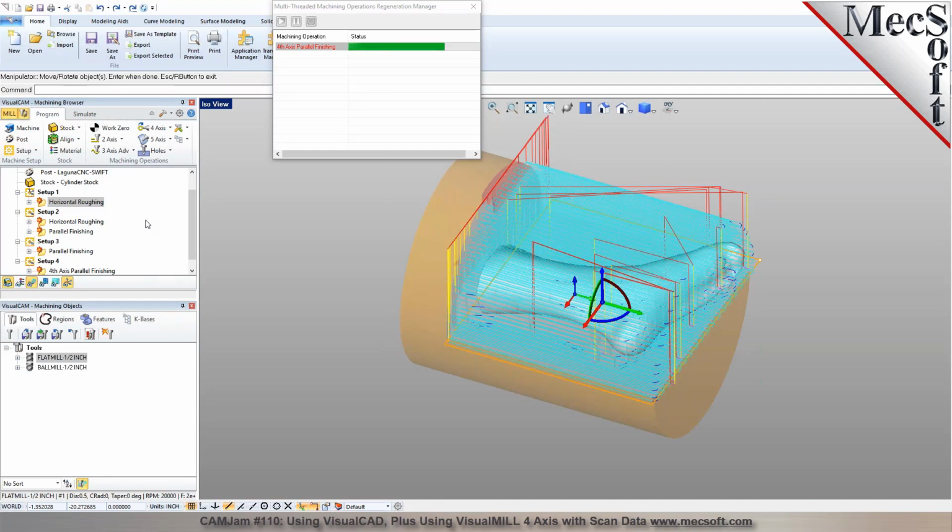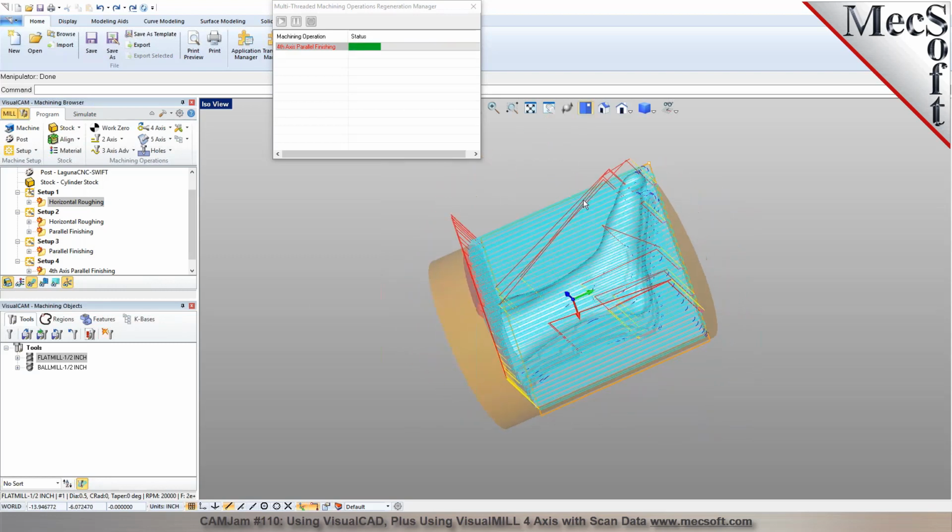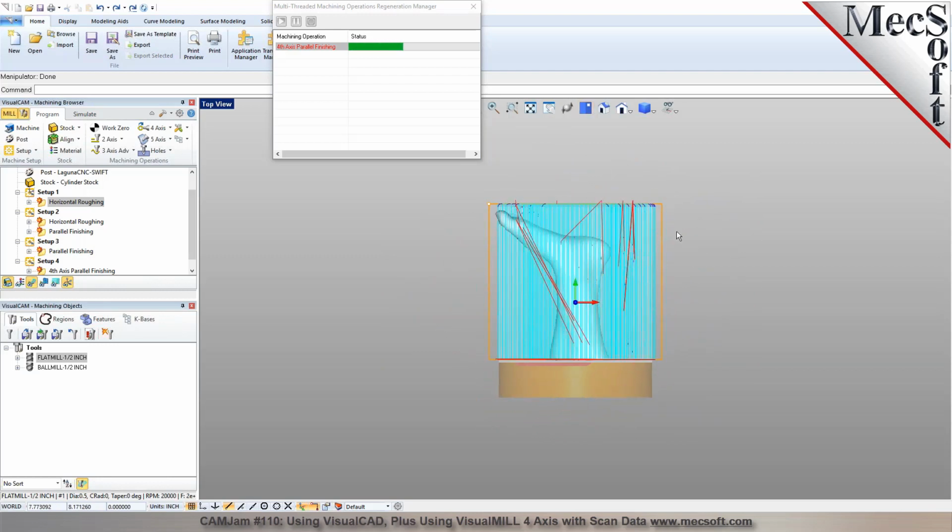The only thing that's going to be different is the geometry you specify for programming, and maybe the length of the stock, based on the scans you bring in, because not all the scans are going to be the same size. So you may have to just recreate the stock, and since we're using a boundary here, you can also modify the boundary for the containment. Okay.